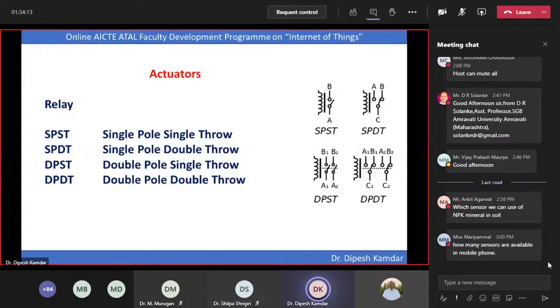If we don't have a system on the other side, we can still use the SPDT. It means if the temperature goes high, we turn on the cooling system. If the temperature remains low, we do nothing, so keep terminal A open and use terminal B with your cooling system.